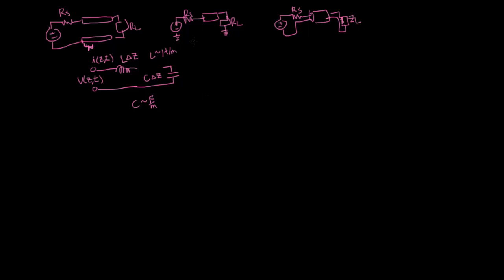So again, current doesn't want to change immediately, the voltage doesn't want to change immediately, and separately, alongside this inductance and this capacitance, they're not ideal inductors and capacitors in that you also lose some energy along there as well. So over here, we're going to have a resistance per unit length, and then over here, just to make the equation look nicer, instead of the resistance, we're going to use the term conductance, which is in Siemens per meter.